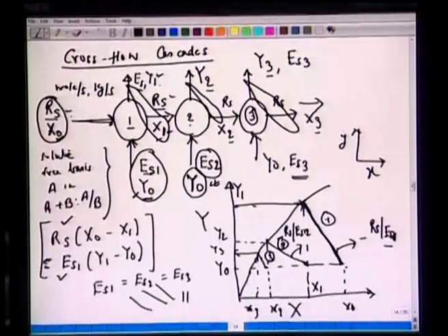And again we want to emphasize here that we are assuming these stages 1, 2, 3 are equilibrium stages. That means all the leaving streams are in equilibriums, and their compositions fall on this equilibrium curve, y equal to f(x). We would like to do the same things now for counter current cascades. In this case again we have the stages. Now, one stream enters the first stage, while the solvent now enters from the last stage. That is a counter current flow.